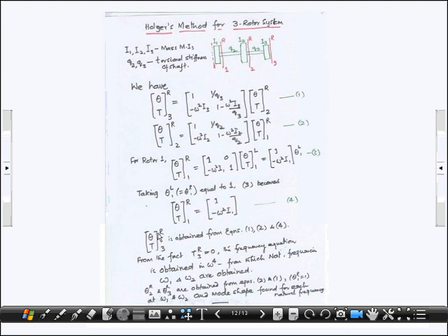That TR3 is going to be only 0. The value corresponding to TR3 that you get is going to be the frequency equation. So TR3 equal to 0 leads us to a frequency equation. Actually, it will be in omega to the power 4, leading you to two values, omega 1 and omega 2, which are the two natural frequencies.